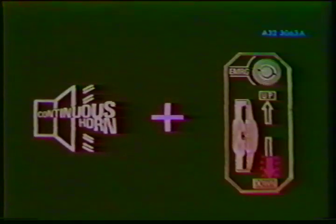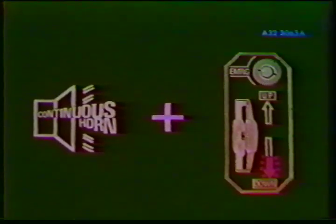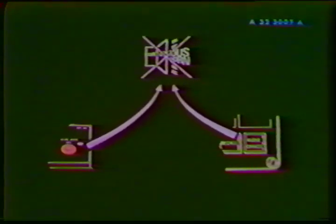A continuous horn and red arrow are activated together in the gear warning configuration. In certain cases, the gear horn can be silenced by the audio cancel on the master warning panel or a gear horn off push button on the right side of the pedestal. The red arrow cannot be canceled except by removing the cause.